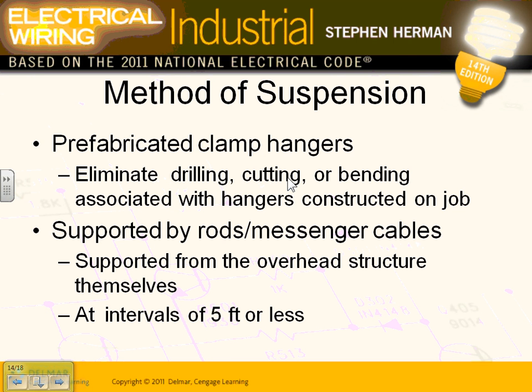Questions? So if these are 10-foot sections, do they need to be torqued on some regular maintenance schedule? Yes, they put them in maintenance. Right here on a big factory floor with dangerous equipment? Well, every manufacturing floor has a cycle of maintenance every 6 months to a year, where they can shut down one section to torque it, to maintain the equipment. All these machines on the manufacturing floor need to be maintained. So they shut down that section. They go section by section, shut it down, torque the electrical system, and work on the machines. You have to maintain them.